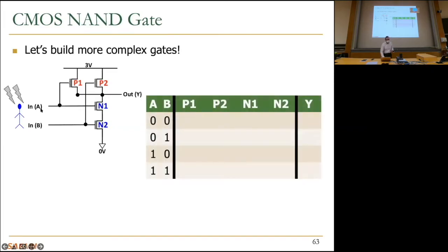So input A and B can be zeros, right? So this is the truth table. Let's build a truth table for this. That's how you figure out what this is. So I already gave you a NAND gate. Actually, your colleague was right. So if A and B are both zeros, let's take a look at what happens first. You need to enumerate all cases. You have 2 inputs, so you have 2 to the 2 lines. And let's enumerate the first case.